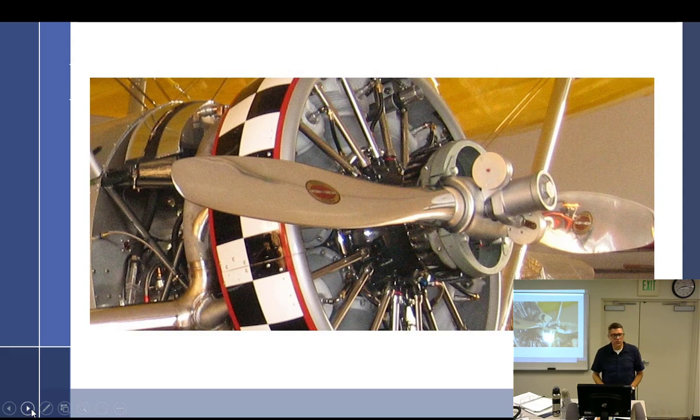Then we have a two-position propeller. Remember yesterday I told you about centrifugal twisting force being the greatest amount of force, and it's always going to make the blades go to what angle? Flat. Unless you have counterweights. Those counterweights are going to want to drop down, and they're going to want to go the other way.